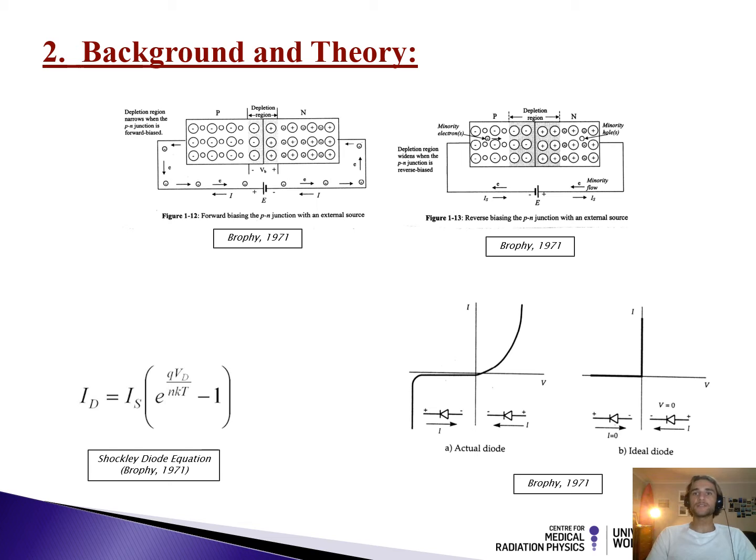There exist many different types of diodes with varying physical properties. A light-emitting diode, otherwise known as an LED, begins to emit photons and illuminate once a large enough voltage allows electrons to cross the depletion region. This value is known as the threshold voltage and varies depending on the color LED used due to the frequency of visible light. A PIN diode is a diode with an undoped intrinsic semiconductor region placed between the PN junction.